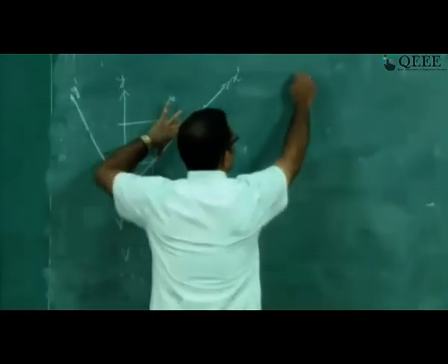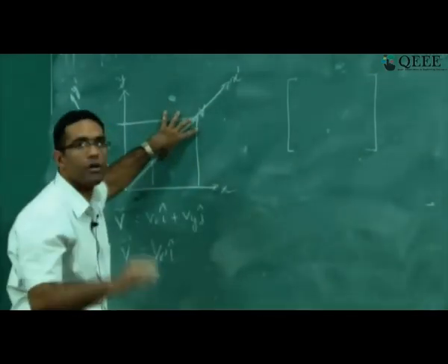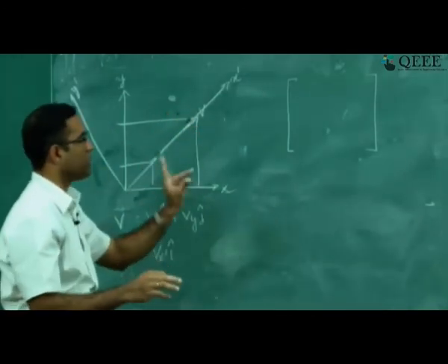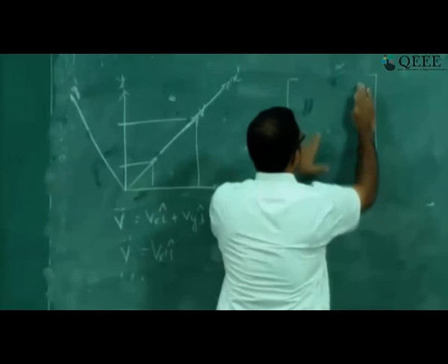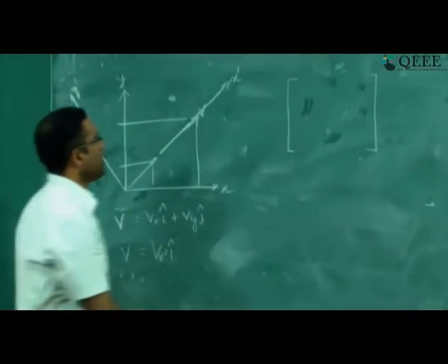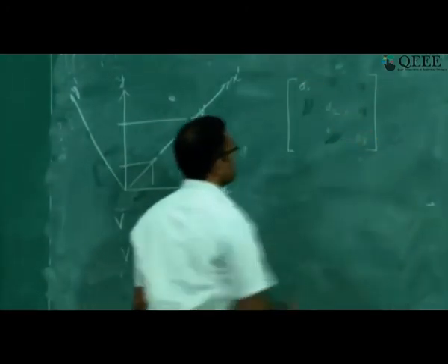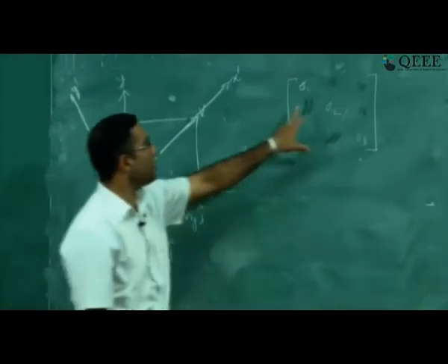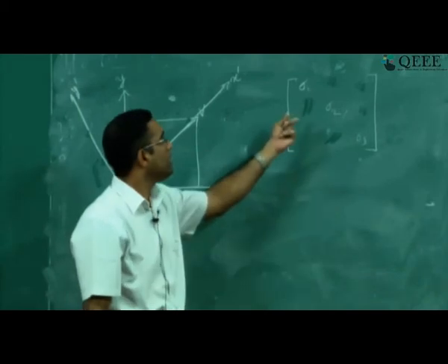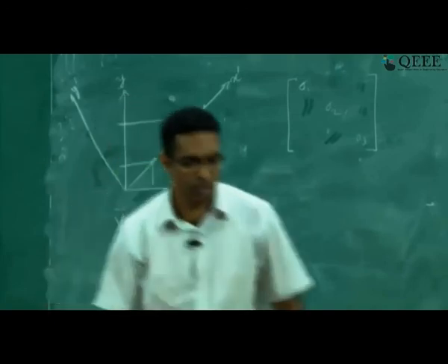In a similar spirit, you have a stress tensor which is written in some arbitrary coordinate reference frame. Now I rotate the coordinate reference frame in such a way that some of these components vanish, the shear stresses vanish, and I am left with only the principal stresses. So now I am in the principal coordinate system. It is still the same physical tensor that I am working with. Therefore, I am not losing any information there. It is still the same physical quantity.